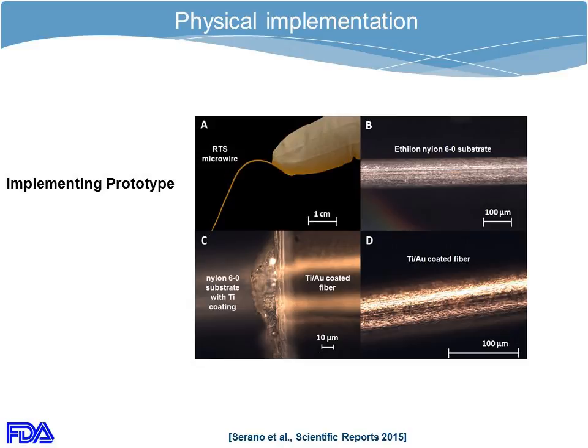So we're playing with the interaction and the difference in the phase and the reflections between the 2 layers that allowed us to make a bad antenna in terms of RF. So a device that will still be able to transfer the current when you stimulate, but it wouldn't be a good antenna in terms of RF heating. And again, if you are interested, you can find additional information in the paper cited below.